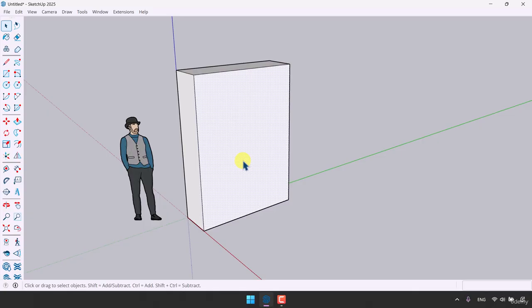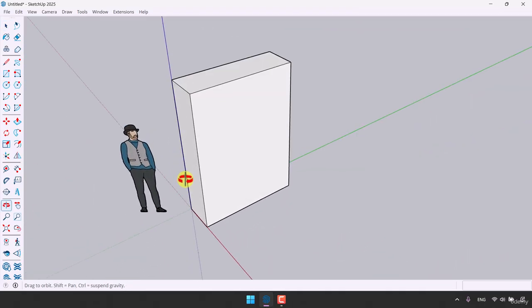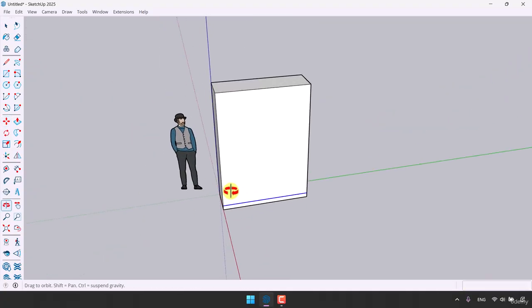Okay, for creating a wardrobe in SketchUp, I need to take some copies and divide my faces. So this is my main face, which I want to make a 3D model of. I can use this character as a scale option and you can see the aspect between them. I think it's logical. So I'm going to click on this line, click on the Move option, and take my first copy from this line. From the ground upward, I think 10 centimeters can be standard for this design.